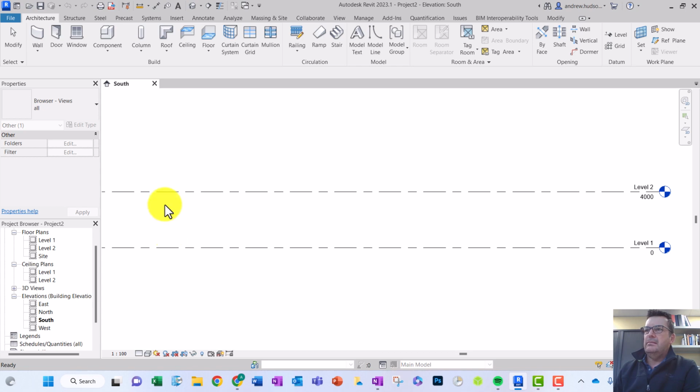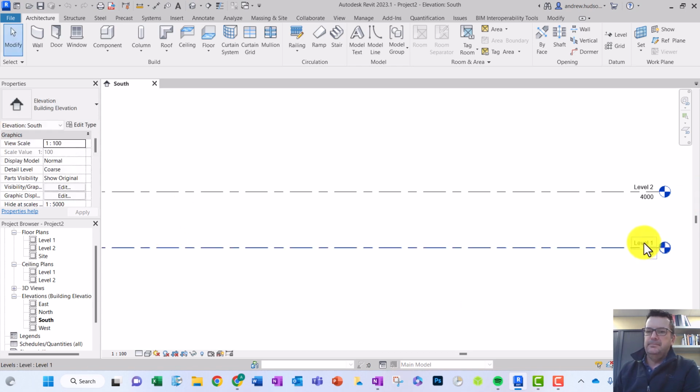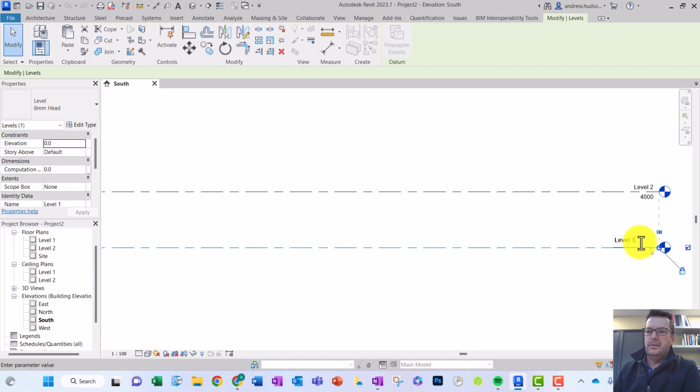And we're going to click on the label that says level 1. Oops, double click that. And we're going to change this. So this is going to now read as the following: 0, 1, and then we're going to have a dash, store floor. You can spell floor, store floor. So we're renaming this level to be those things. Once we've renamed it, press enter.